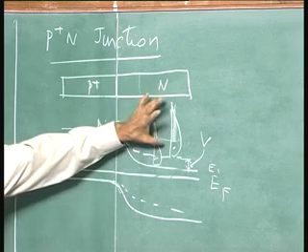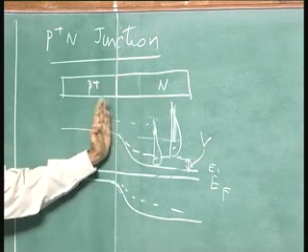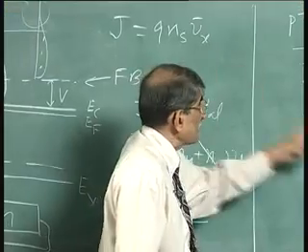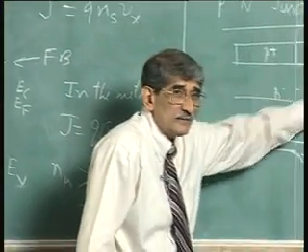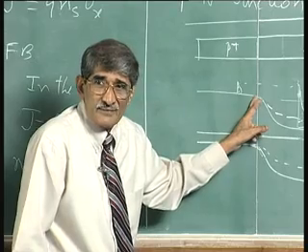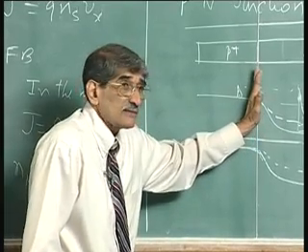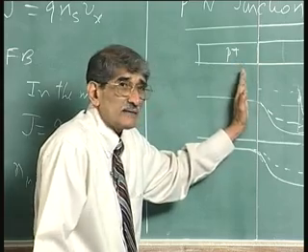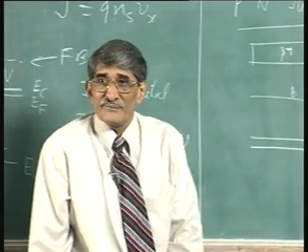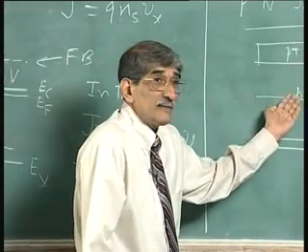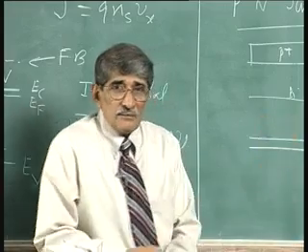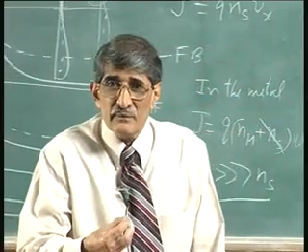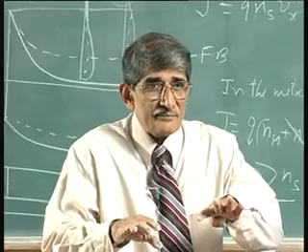the reason is these electrons which are impinging on the surface with the same equation, q ns, ns is actually this quantity, q ns into v of x. They are striking the surface, they are able to cross the barrier, but having crossed the barrier, they find that they are minority there. Once they are minority, how much the current is depends upon which of them is larger.